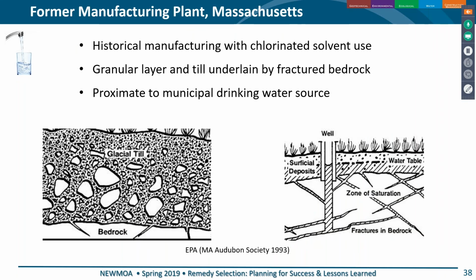It is, like a lot of my sites, an old historic factory that manufactured equipment back in the 50s. The site was vacant through late 90s, early 2000s. And we have blasted rock, kind of granular fill, glacial till underneath that, bedrock underneath that. The till is, you know, really, really tough. It's really dense, sand and silt. And the bedrock is more like moderately fractured, moderately weathered, granitic gneiss, and it's got some steep angle fractures.